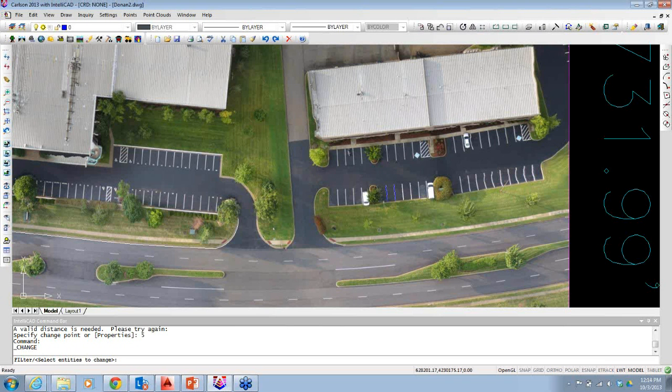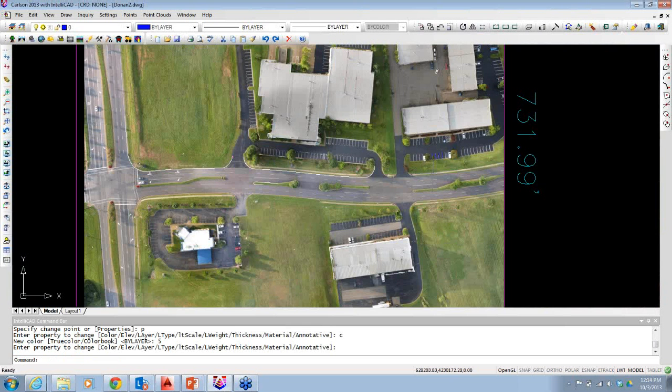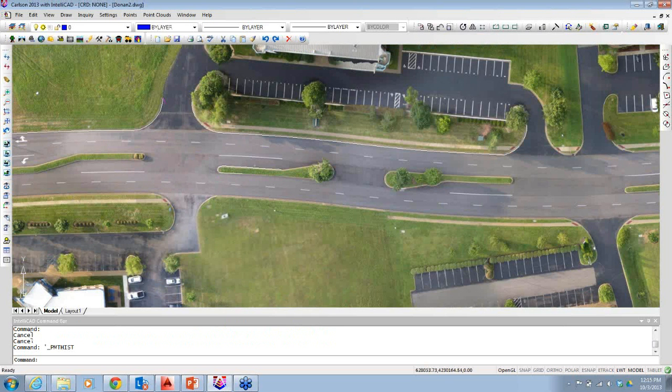Okay, and you can see that I just added 2 lines on the geo-reference TIFF file, and you can see over here I have my polyline that I drew right here. And if I list this guy, you can see that it came across with elevations, escape, and that's pretty much how, we'll go back to the PowerPoint presentation, how the Action tab works, where you can actually pick nodes or dots in the point cloud individually and draw points and or line work.